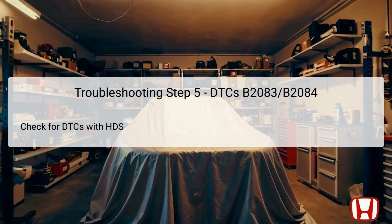This step is critical as it provides real-time insights into the performance of the right power sliding door system based on the actions taken in the previous steps. If DTCs B2083 or B2084 reappear, it signifies that the system is still experiencing malfunctions that need further diagnosis. The specific codes that appear can offer clues as to where the problem lies, especially if they indicate either a control unit failure or persistent electrical issues.